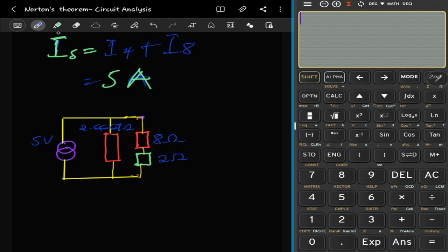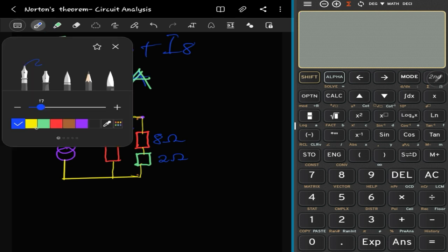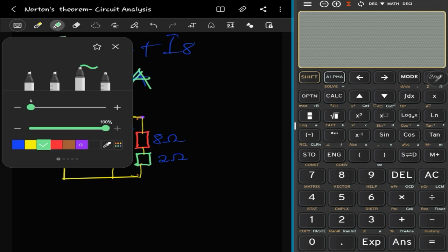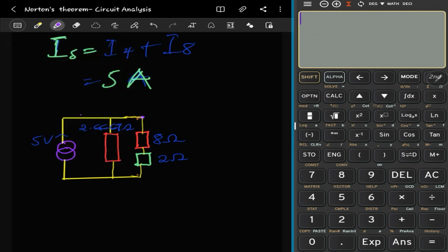So now we found this 5 volts here, but then this is the only voltage source here, right? So as current moves, it moves in this direction, but when it gets here, because there's one resistor here and a resistor here, it actually splits, right? So we get a current here, so current division. So if our aim is to find the voltage across the 2 ohms, we should be able to, V is equal to IR, right? So meaning we should be able to find a resistor, which we know to be this 2 ohms here, but we need a current, right? But in the current, this current from the 5 here comes here and then it splits to these 2.